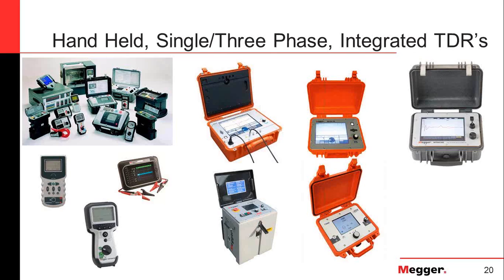Well, when we talk about high voltage power cables, you could pretty much use... well, let me back up a minute. This is actually a good page to answer that. Here you can see a whole bunch of different TDRs. Over here on the left-hand side, we have these little handheld TDRs, and all of these TDRs would look down the same cable. But here on the right-hand side, these TDRs are specifically designed to work in conjunction with that high voltage pulse from a thumper.